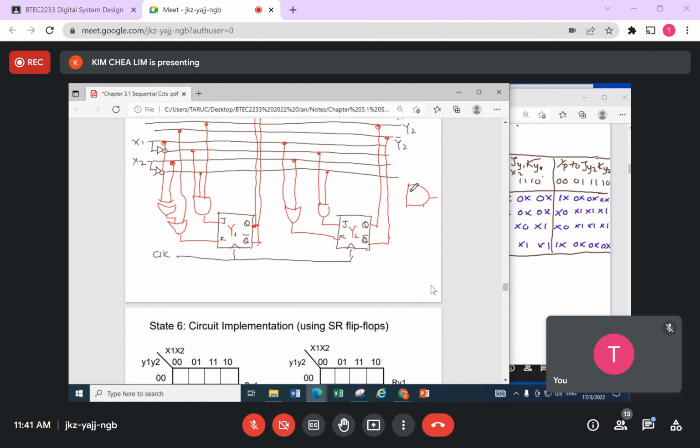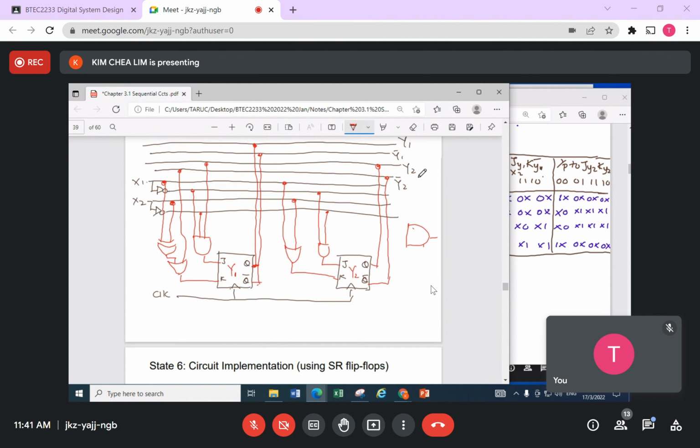All right, so your AND gate here, you connect to, so follow sequence on top first, Y1. Over here, I don't want to join them, so I just label accordingly. I join it to Y1, I join it to Y2 bar, I join it to X1. Okay, I join it to my X2 bar. You can join them or you just label, and my output here is the Z.